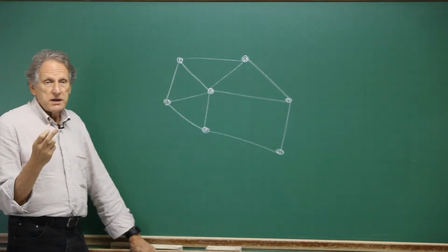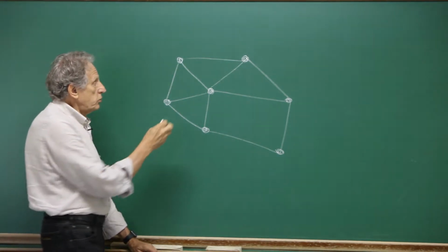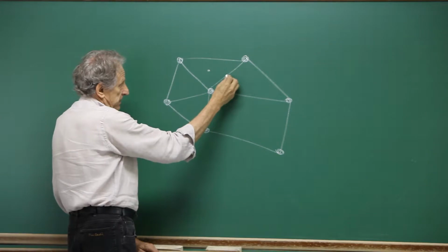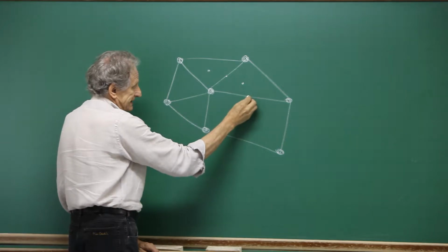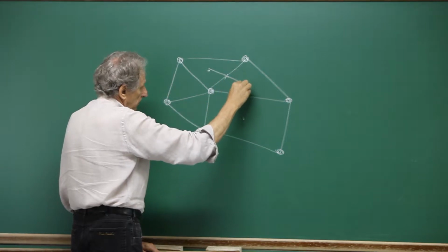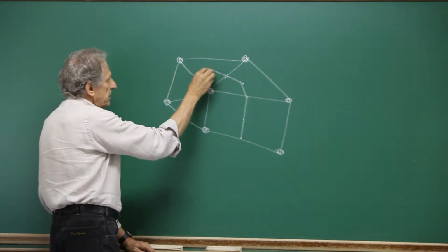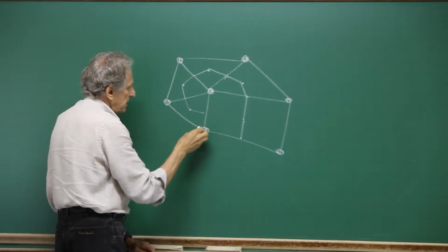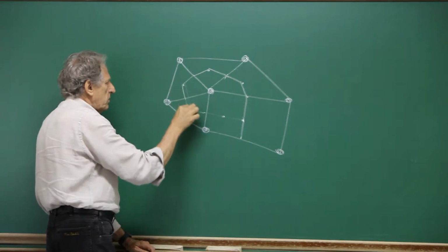Now you have to choose a way to create the control volume. In the element-based, what you do is find the center of the element, the median, the center, median, and then you join. You join, and then keep going: center, median, center of the element, median, and then center and median. Here's the control volume.